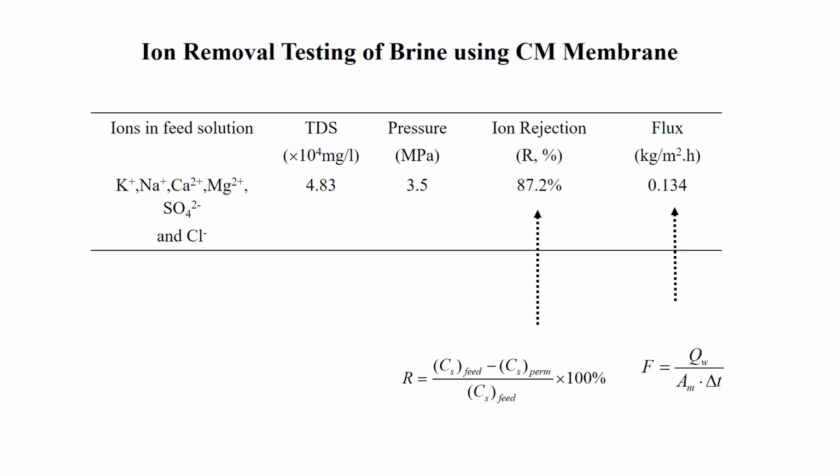So we wanted to ask: can this new type of membrane we produce treat the brine without incurring any additional high pressure? As the previous speaker also highlighted, because the concentration of the brine is quite high, you need a very high pressure in order to treat it using a reverse osmosis membrane. So we wanted to see if the new membrane we're synthesizing in the lab could be used to treat the brine effectively, but at a lower pressure. And that's what we did.